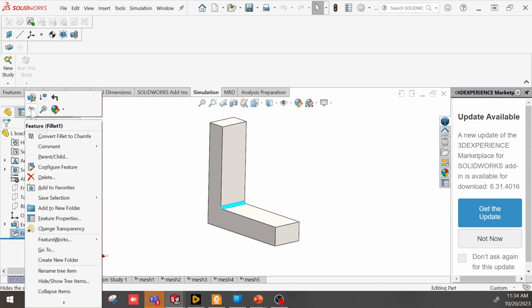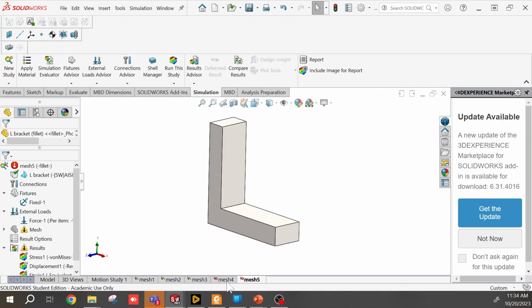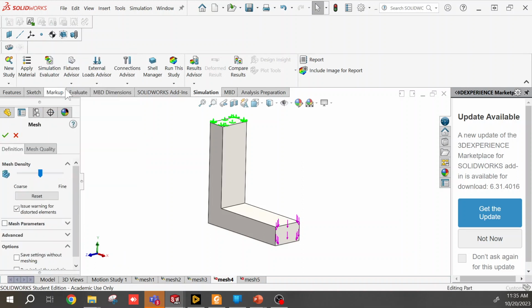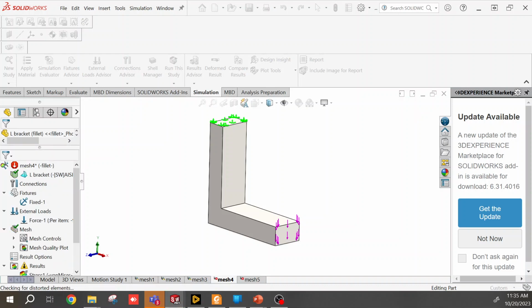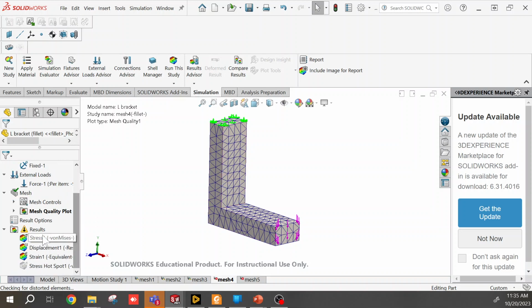Okay, so we will suppress this. We will create the mesh. And you can see under the mesh toolbar, there's a warning here that you can say, issue a warning for distorted elements. If we wanted to make it slightly finer, in this case, we could do so. It'll take a little longer to mesh. And now I think it's placed 4 elements across the thickness instead of 3. You can play around with that and do it a little better if you want.